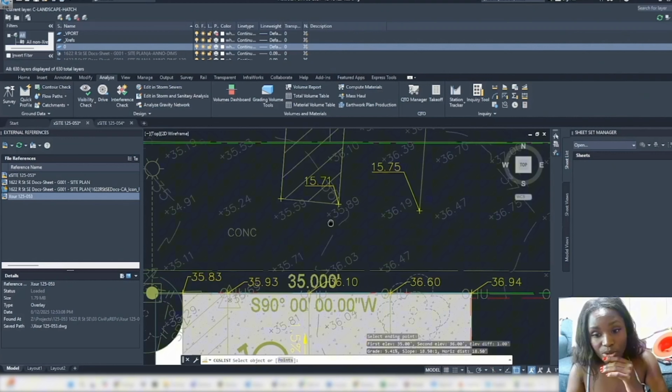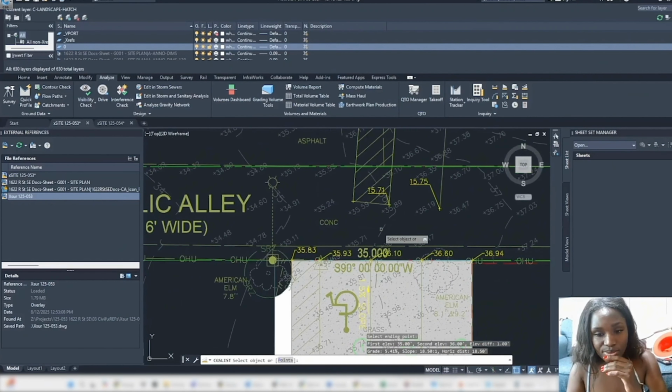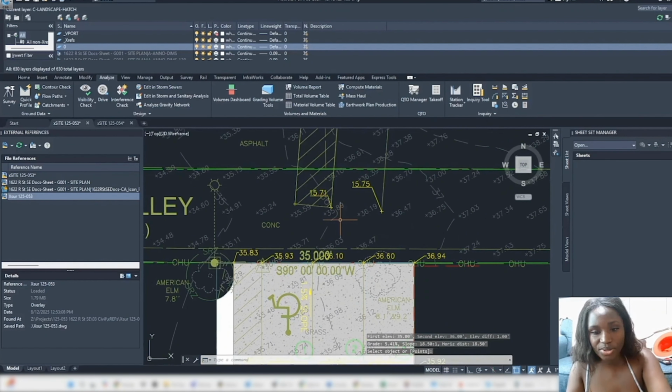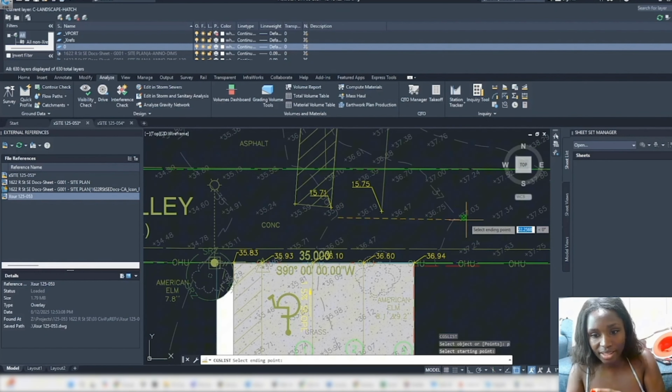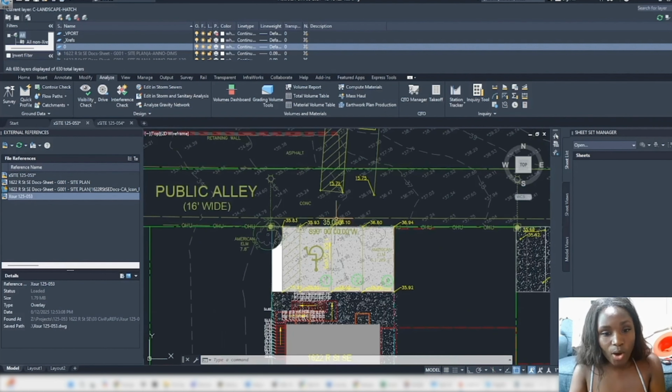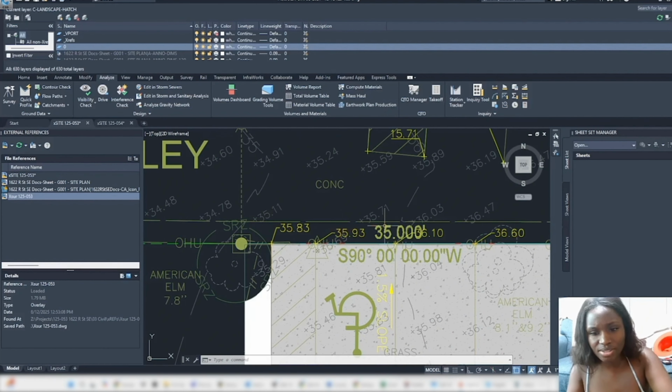So let's engineer something. More than 5% slope. But that's the reason why the slope is already so high. So we have to then make up for that slope here. And the only thing we can do is potentially have an apron at the face of the building, probably like that face, but actually we can't even do that. Usually we can do an apron that's 2% cross slope and then go down. Oh, also, never mind. This has to be concreted.